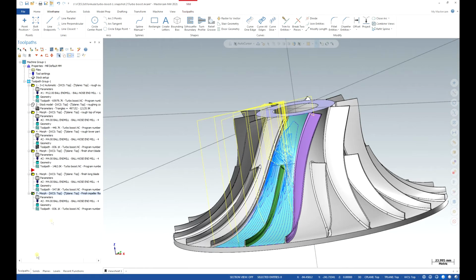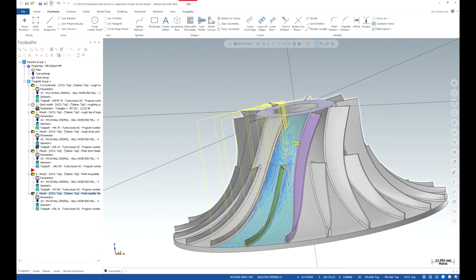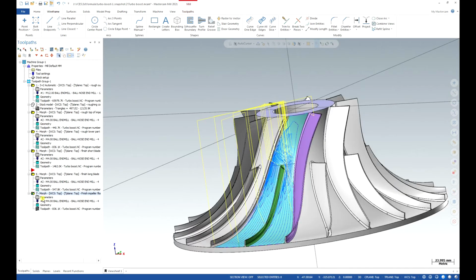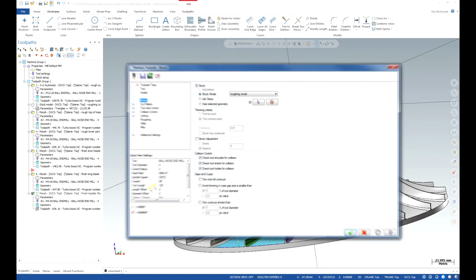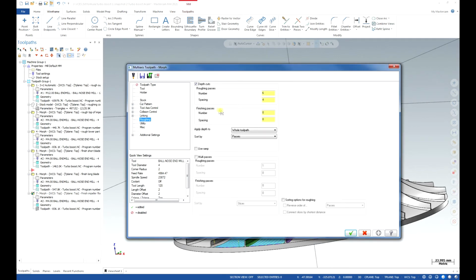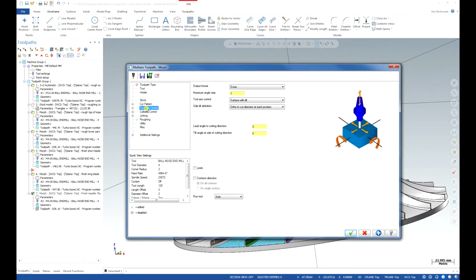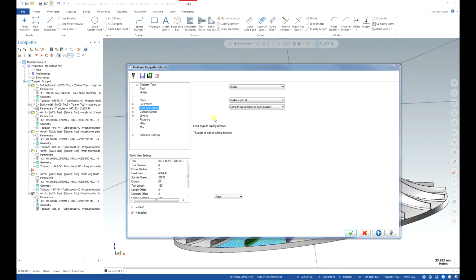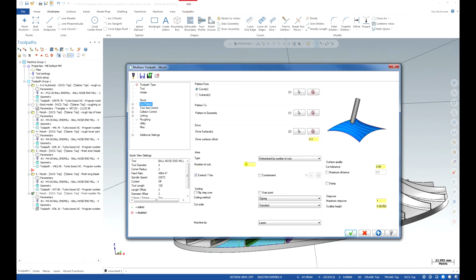First, we are going to remove our roughing cuts from this section, from the floor, as the whole floor has already been roughed out. So I'm going to switch off in roughing page, and the tool axis control all is good. Cut patterns, we are going to switch the type of the pattern to full, avoid cuts at exact edges.